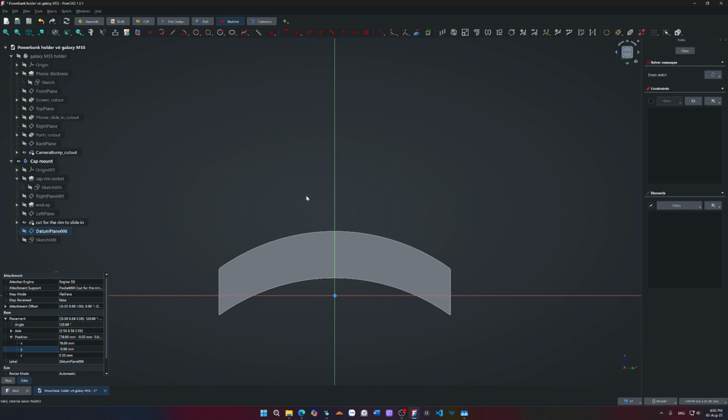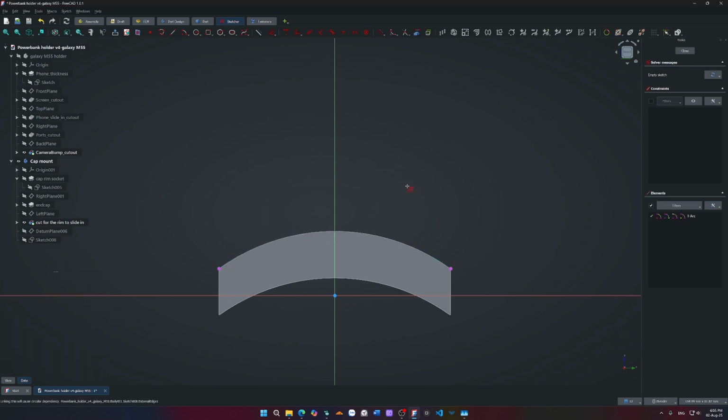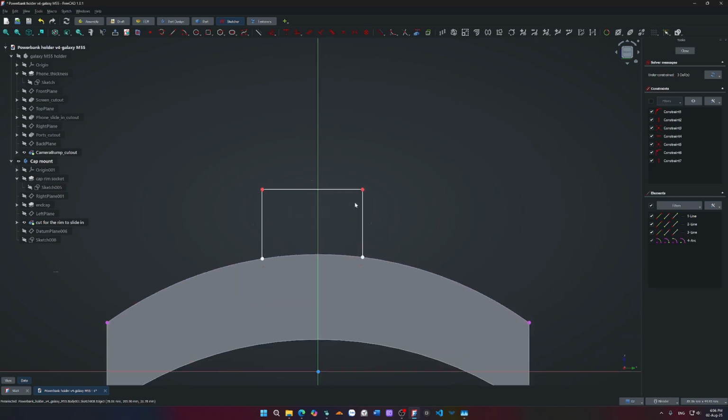And I will make a surface based on this thing alone. So GM, no, should have set the auto constraint, control Y, boom, now vertical, baby, let's go. These two will be symmetric to the center line. They should have the dimension of 10 millimeter.